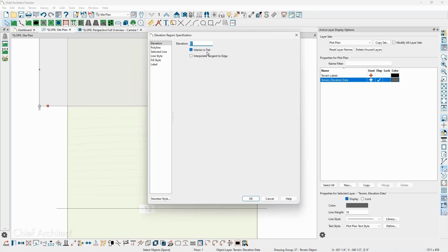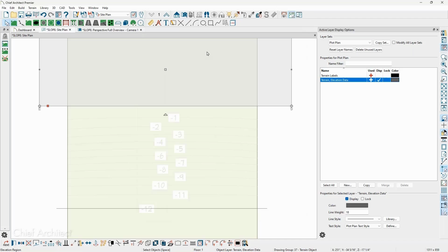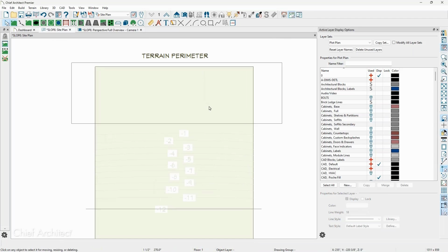So basically, when I get the shark fins, I've just put my lines and the regions too close together. Most of the time. I wouldn't say all the time, because sometimes there are little gremlins in terrain things when you have terrain walls or retaining walls, and it does take a little bit of looking into. I oftentimes will turn off the layers for those walls so I can see exactly where some of those issues get generated.